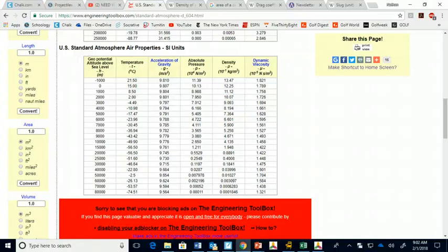So, what do you see? Just taking a quick look here. As the altitude is increasing, what's happening to our density? Significantly decreasing, right? Which makes sense, right? More air down here with us, less air the further up we go, right? So it would actually be a bit of a sliding scale. Now our rockets are probably only going to get up in this range, 5,000 to 6,000 feet. But there's definitely a difference, right?